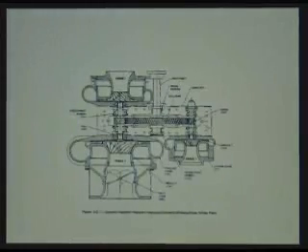One of the other compressors for centrifugals, sometimes used in process, mostly we see it in instrument air, is called an integrally geared machine. What you have is a motor that drives the shaft into a very large gear, which then spins several pinions at a very high velocity. And so these are all a bunch of single-stage wheels that are hung off of the gearbox, so you'll have gas passage into stage 1 and then out again, and through a cooler into stage 2 and then out, and then into stage 3.